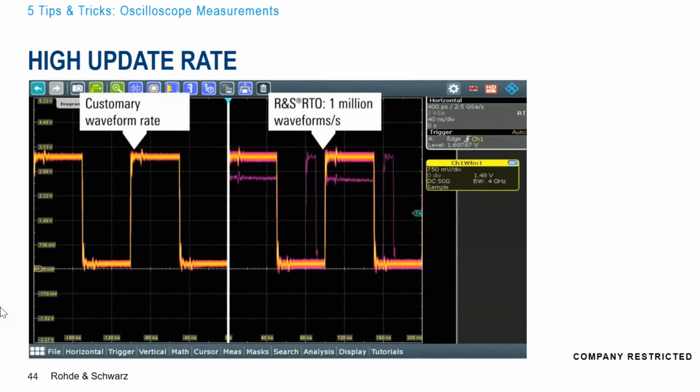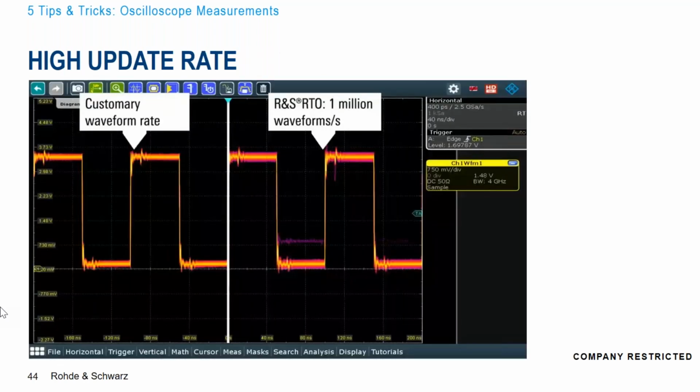So we can take a look at this on the scope, but what happens is that because we're only taking full captures every once in a while, these glitches can sneak in between captures of the oscilloscope. So during the time that an oscilloscope is processing the data and getting it to the display, you might miss all this other stuff that's going on. So one of the big things we can do is, once you see it, just during normal operation, you can go and dig in to the deeper details happening. So this makes a digital scope feel a little bit more like an analog scope where you saw everything. Digital scopes for the longest time had been very, very slow to update. So they're great for post-processing, getting data off, but very difficult to get that lively feel. We have very few slides on this one, but we can jump back over to the scope because I think that's much more fun.